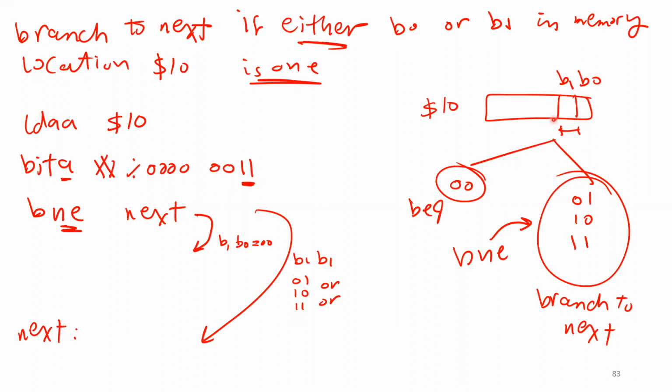What I'm going to do is check these two bits. So I'm going to put 1, 1 and 0 everywhere else. Now, with branch if equal, if the result is 0, what does it mean? It means these two bits are zeros. Because I put 0 everywhere else, forget this part, this part will be 0. And the byte I'm going to get is bit 0, bit 1, and then 0 0 0 0 to the end. So if I get 0, that means the two bits here are zeros. If it is not equal, that means the result is not 0, which can be 1 0, it can be 0 1, it can be 1 1, it can be any of these.